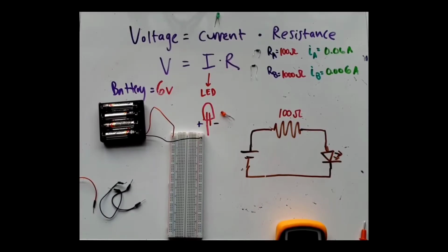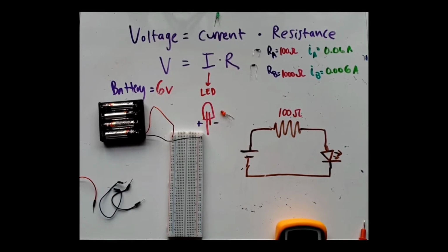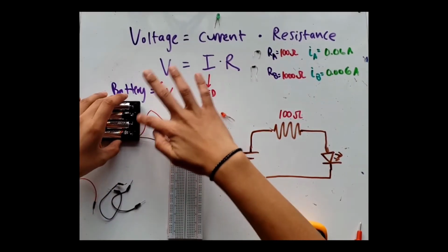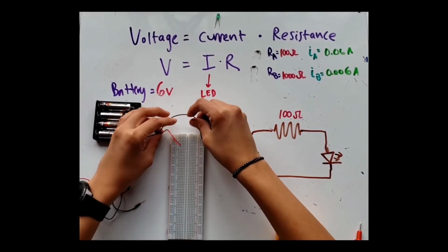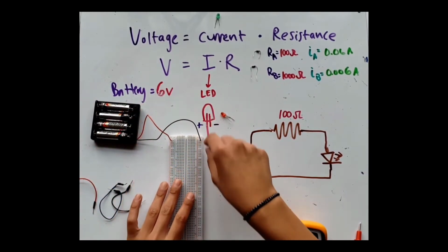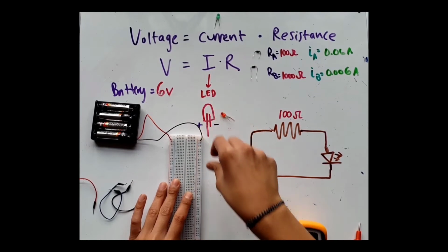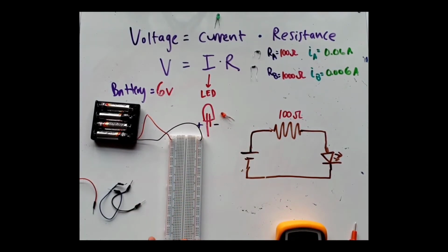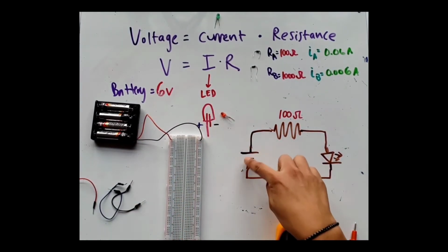We'll combine the topics from our last couple videos into a hands-on circuit that we're going to build on this breadboard. Okay, so you get the battery. The positive end is going into the positive rail here, the plus sign, and the negative sign or ground is going into the negative rail here. So this is what it looks like when the breadboard is powered up. Okay, that's this battery component.